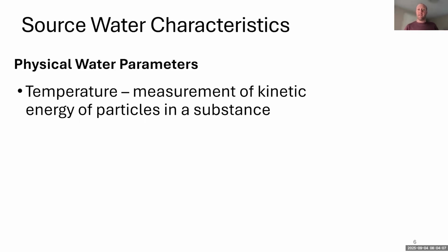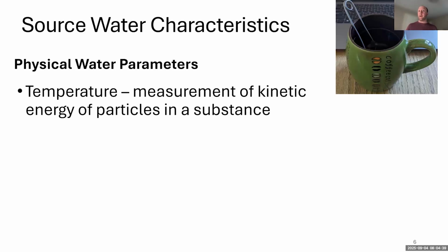This is important for many reasons, and probably most importantly for drinking water and for our purposes, the warmer water is, the more quickly reactions take place. In order for chemical reactions or physical reactions to take place, they utilize energy or they give off energy. But the warmer the water is, the more energy is available, and the quicker reactions take place. Of course, we kind of intuitively know this. If you think about brewing a cup of tea or a pot of coffee, it's a heck of a lot easier to brew a cup of tea using hot water than it is cold water.